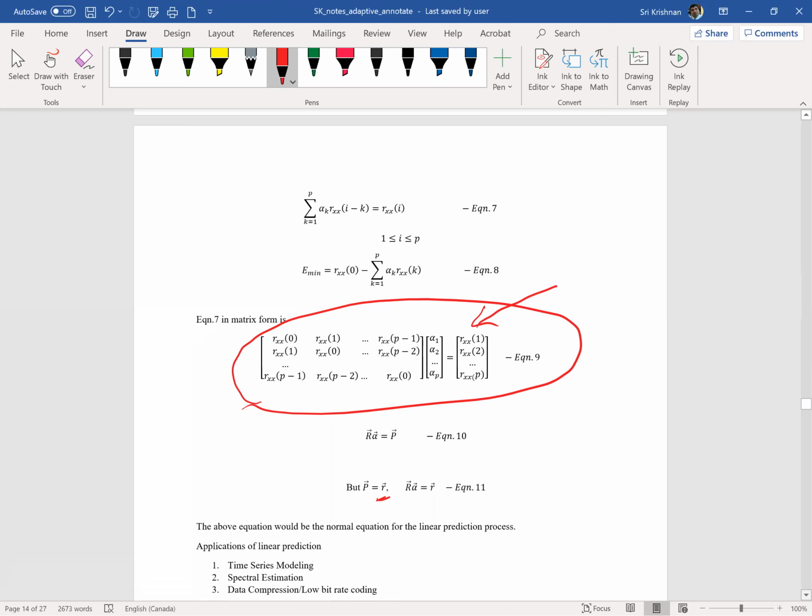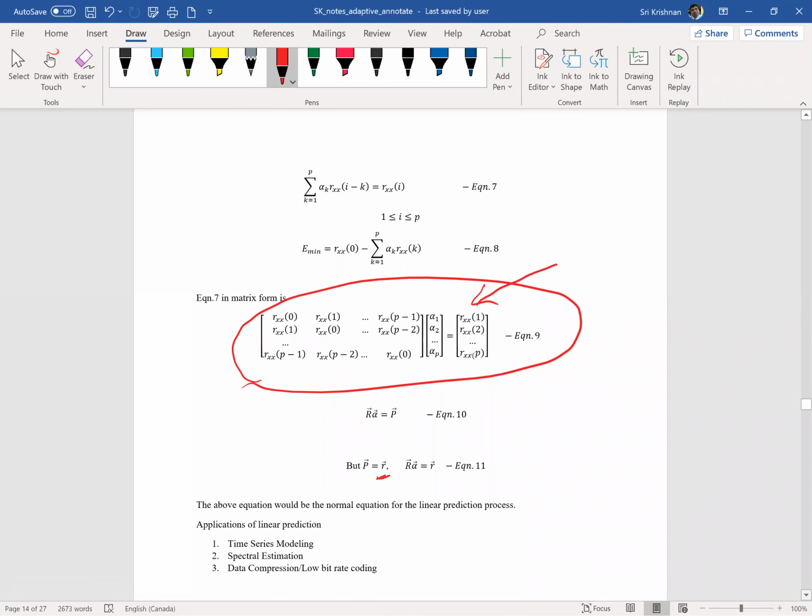It's not the signal multiplied with itself. It's delayed by 1 unit, 2 units, and so forth, and we take those values. So it's the same thing. Nothing has changed from what we have seen before, but once we determine the alphas, the alphas are acting like a predictor. So if we send the signal X into this filter with alpha as values, it will give us the next sample and so forth. So that is a very neat concept.